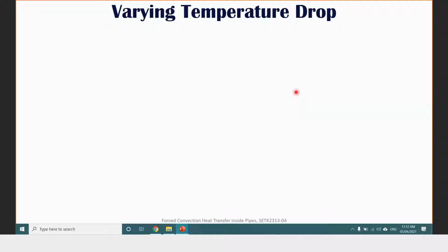Okay, so if we have fluid flowing through a tube, but we want to have a difference in temperature, outside the tube we have another bigger tube where we flow in either hot fluid or cold fluid, so that there are changes in temperature inside the inner tube.